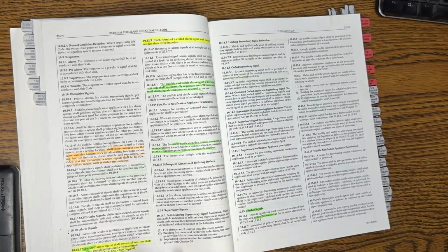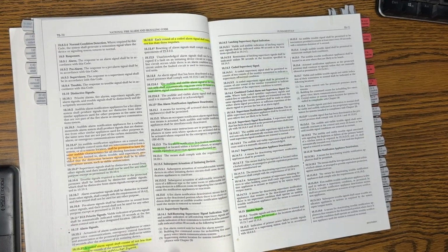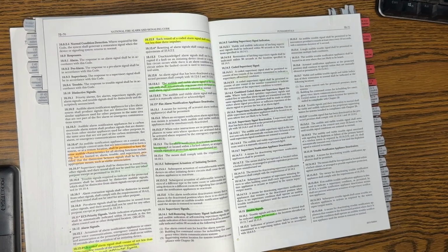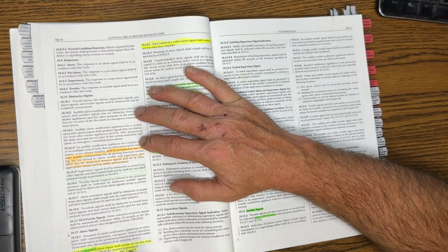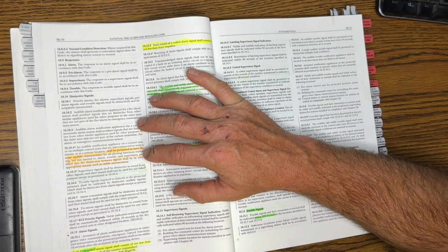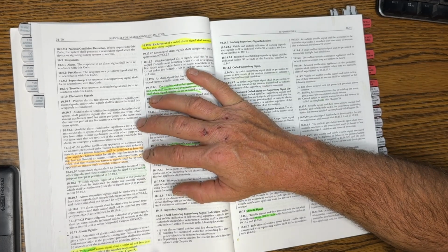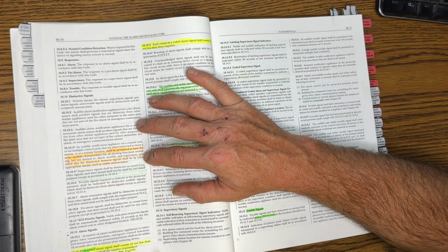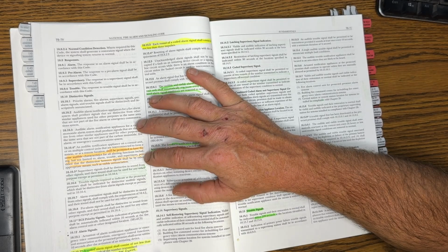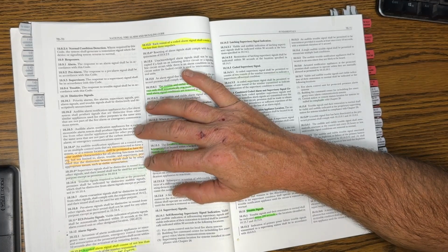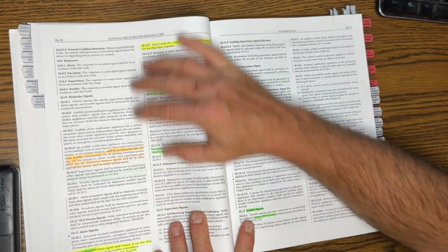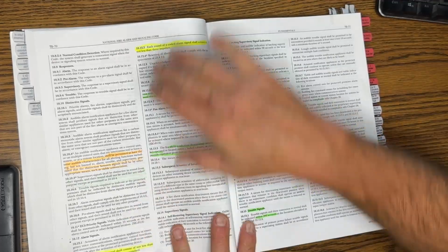So let's use an example. Let's go 10. In the discussion earlier, I talked about NFPA 72, section 10.12.2 and 3. So right here. So the question was, a coded alarm signal shall consist of not less than, well, what is it? 3. The answer was 3 complete rounds of the number transmitted, where each coded alarm signal shall consist of not less than 3 impulses. Obviously not an emergency voice alarm system. So this would be a coded alarm system. And they do still exist, gongs, things like that. But that's how I set up these questions.